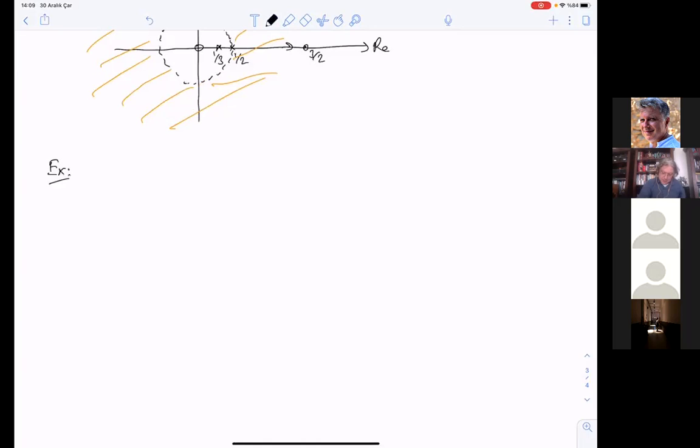And in this example, we will see that x of n is equal to 1 over 3 to the power n times sine pi over 4 n u of n. Okay, so how can we really find the Z transform of this one, and how can we relate it to something already in an exponential form?